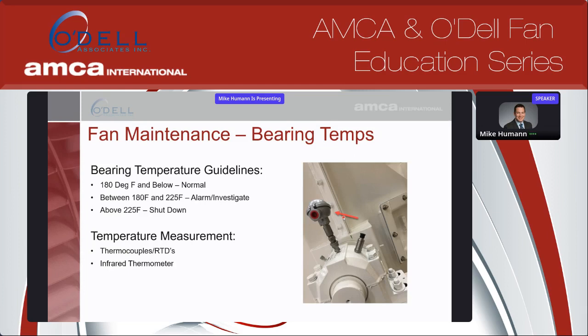You can also use infrared thermometers, but realize that you're only looking at the external temperature at that point, so there is some offset there. We see about 10 to 20 degrees of difference between external temperature and internal bearing temperature. So something to consider. Not all applications have RTDs or need them, but an infrared thermometer can also help you monitor the temperatures that the fan and motor bearings are seeing.